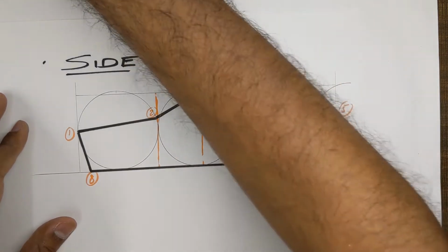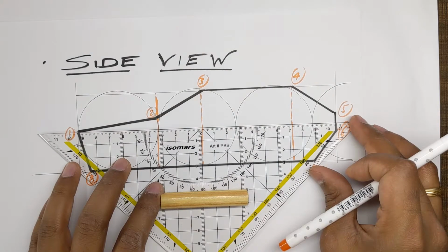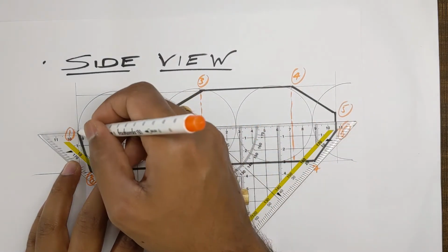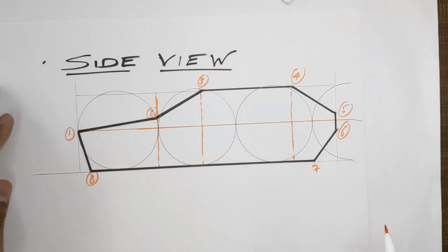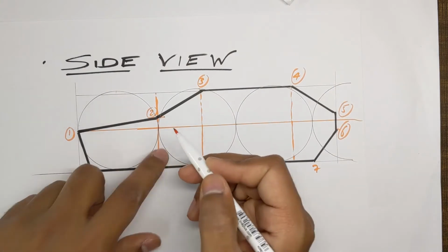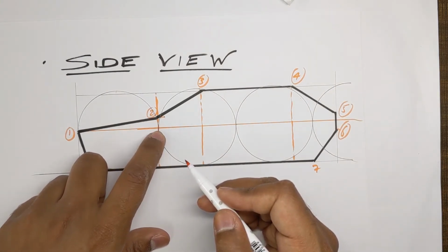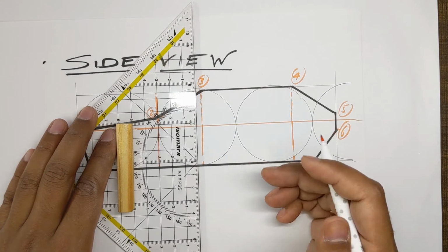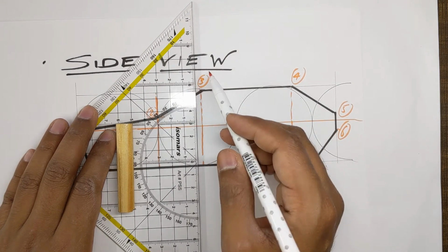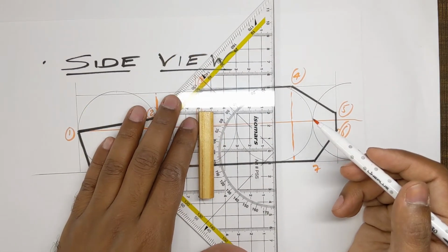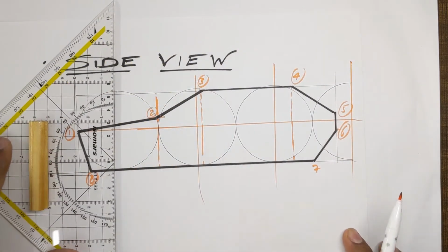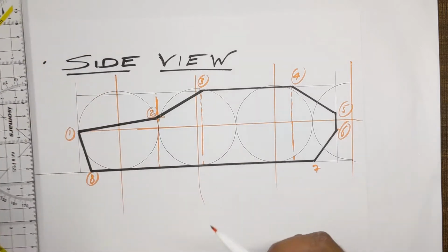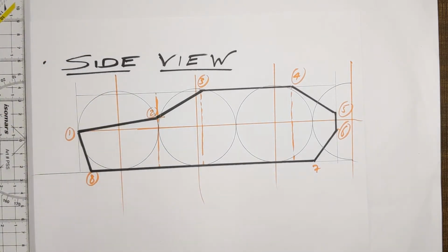and similarly over here, like this and like this. And to just make my life a bit easier, I'm going to draw a line which goes through the center of my circles, so I have some reference as to how high my point number 2 is from the center line. I'm also going to do the same for my circles over here, and the center from the first circle. Alright, so I hope you get this idea.